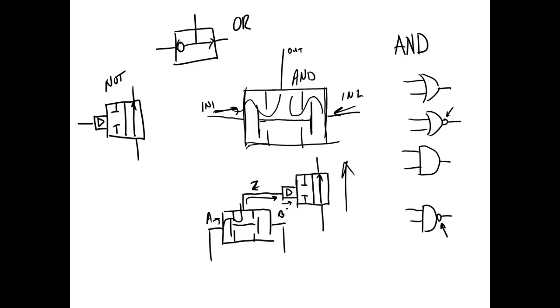They don't change power. They step the voltage up. If they step the voltage up, the current goes down. If they step the voltage down, the current goes up. That's what transformers do. They don't change the power. If they were 100% efficient, if I take 100 watts out of it, I'm putting 100 watts in.